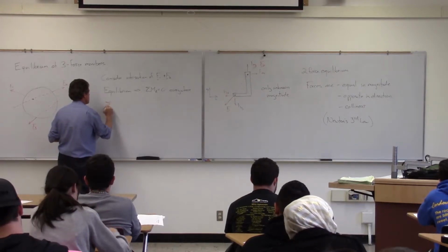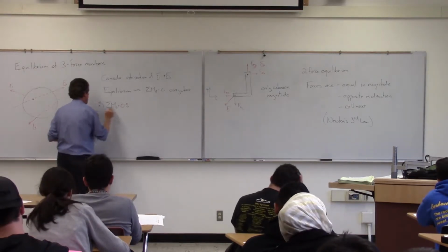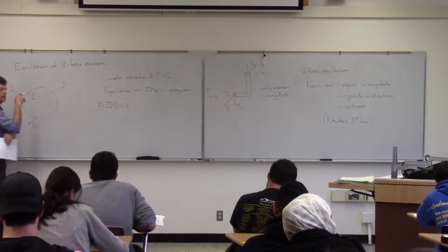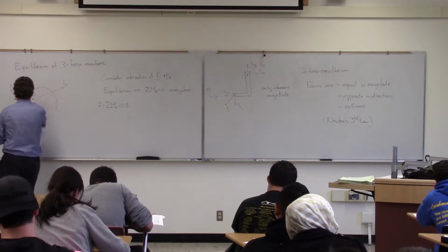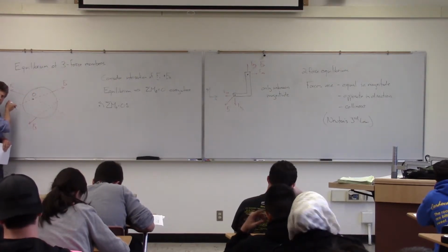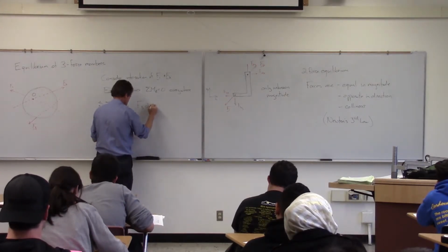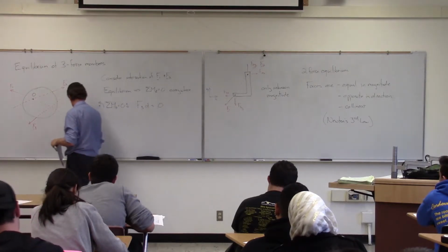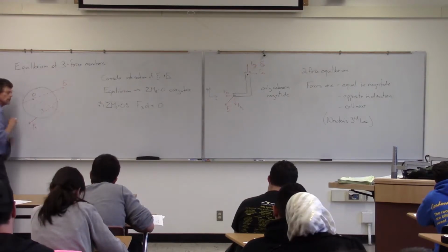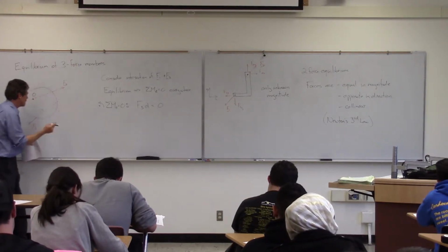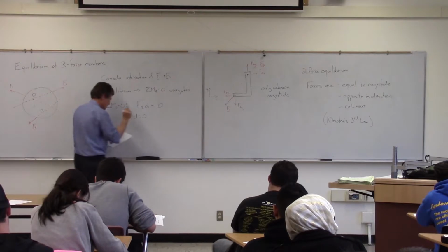So let's consider taking moments at this intersection O, we'll call this, of F1 and F2. And again, in terms of the moment equation, F1 will not participate, F2 will not participate, because there's no moment arms. What I have is F3 times some unknown distance, again. So that would be my D, that perpendicular there. But what I'm finding again is if F3 has a value to it, then what that's saying is that D is equal to 0.